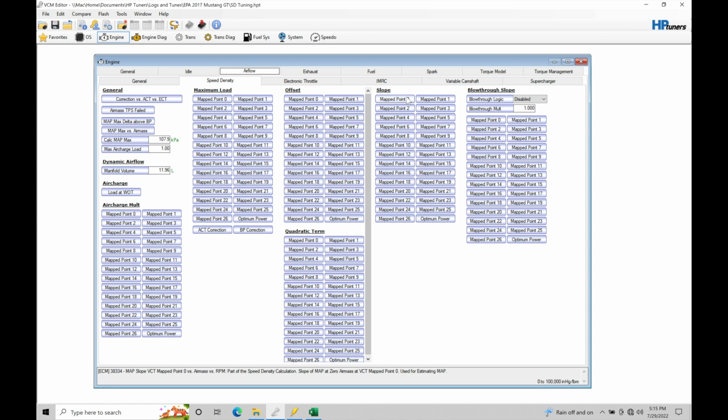But in our Mustang applications, we have a mass airflow sensor that's fitted to the intake track of our engine. In fact, we've calibrated that already. We understand what that means and how that works. Well, the way this is going to work with the speed density type of calculation is that the mass airflow is registering the airflow coming into the engine, using the mass airflow reading as more of a steady state airflow registration. The mass airflow sensors are excellent at measuring steady state airflow.